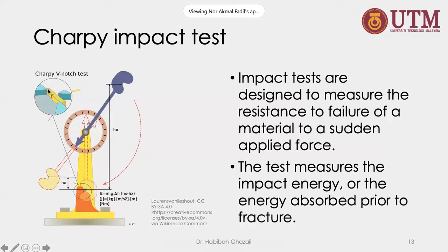Okay, we don't want it to be cracked at this point or this point, because we want it to be following standard. When you want to create a standard, you must design a standard that can be followed for any materials. So when you create the notch here, every sample, every material that you design will follow this standard, and it will fail at this point. So when we give a load directly at this position, the crack will occur here.